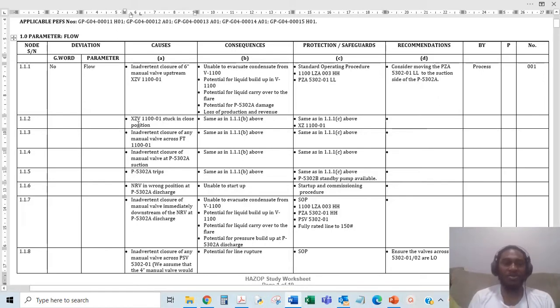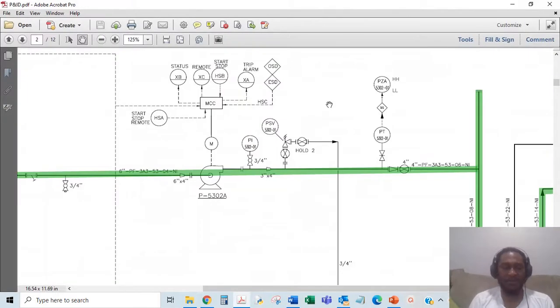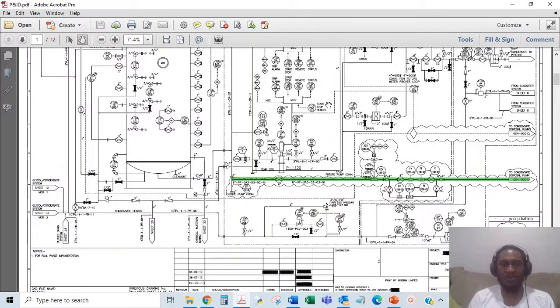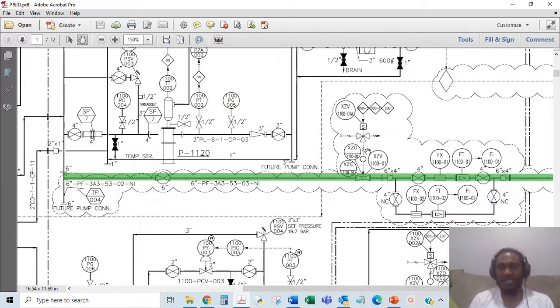That's why. So this is an XZV110. That's the shutdown valve downstream the surge vessel, and that's it here. So this is a shutdown valve. It's electronic or instrument air, and it's controlled. So this doesn't have anyone coming to open or close it. It works by itself. So as this is a shutdown valve, sorry, I'm pointing at the screen, I should be using the mouse. So this shutdown valve not working gets stuck in closed position.